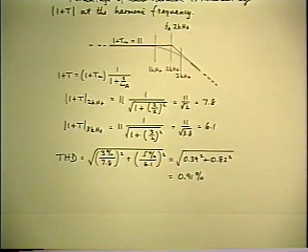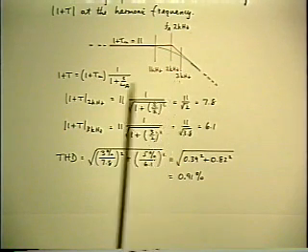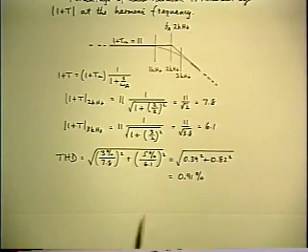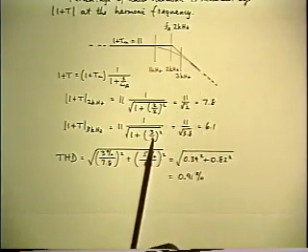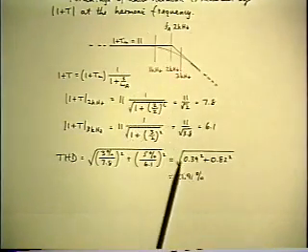And once again, notice that in spite of the fact that the closed loop gain bandwidth is flat from 2.7 hertz to 22 kilohertz, it's still a crummy little amplifier. Because not only does the output impedance rise outside the much narrower mid-band range for TM, but the distortion reduction factors also decline outside the same narrow range.